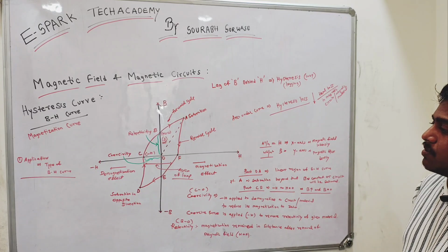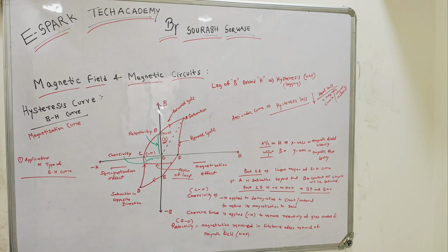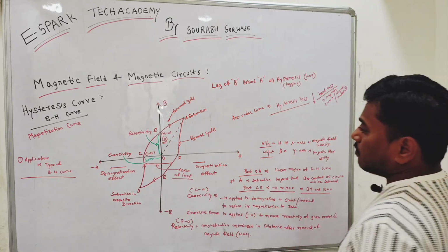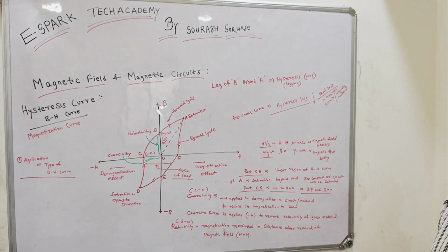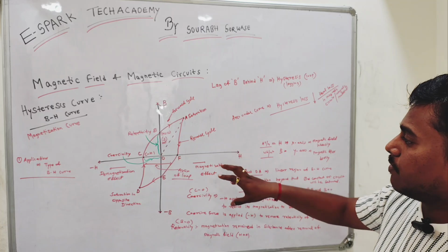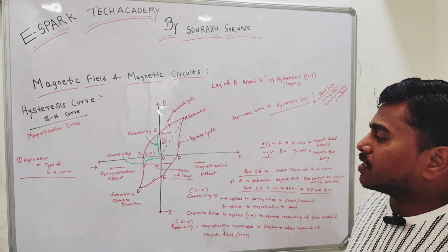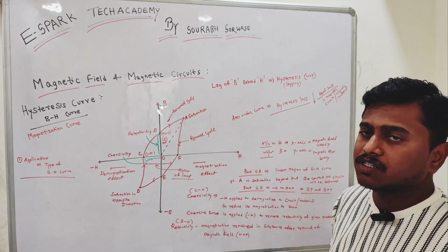During the cycle of magnetization and demagnetization, energy is spent and the spent energy forms in the form of heat. Now, what we have done is we are magnetizing as well as demagnetizing. Both effects are considered during this hysteresis test, meaning plus H as well as minus H, and during that effect some energy is spent.